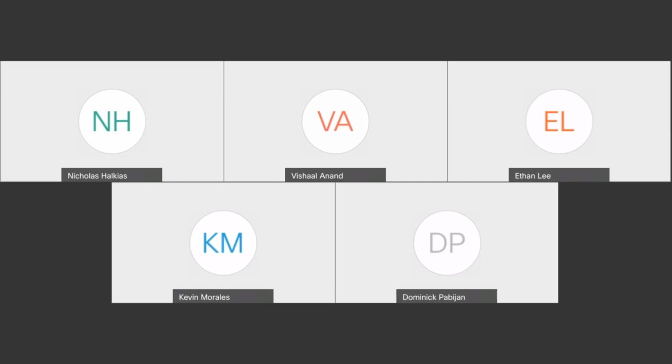So you can use this on any part, which would be found in the 3D modeling ribbon. And it'll be all the way to the right, stress analysis. I don't have a picture of it, but you can also use it for an assembly. And in the assembly, you'll have an environments tab, and that's where you can find the stress analysis for an assembly.